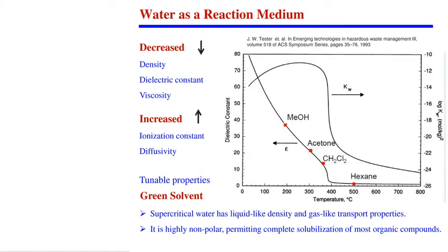If you want to make bioethanol, how can we use hydrothermal or subcritical water? If you have a woody material or grassy material, that means it has hemicellulose, cellulose and lignin. And if you want to make ethanol, how can ethanol be made? Cellulose and hemicellulose will be the source of sugar and we will ferment it. But what to do with the lignin? We will have to separate it. Before we ferment, how do we release the sugar? We will need enzymes to work on it.